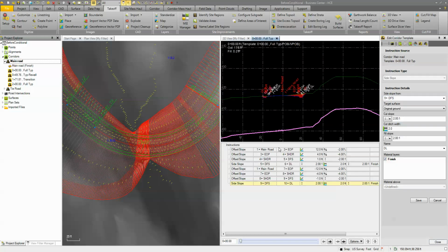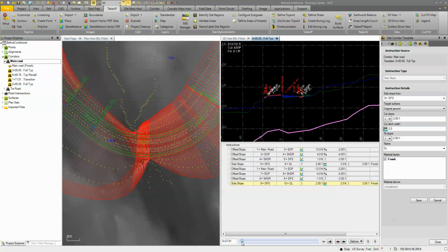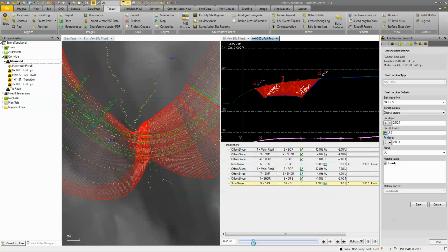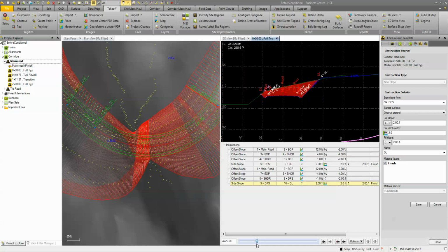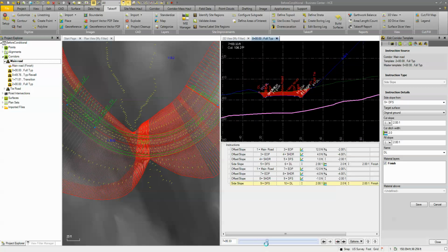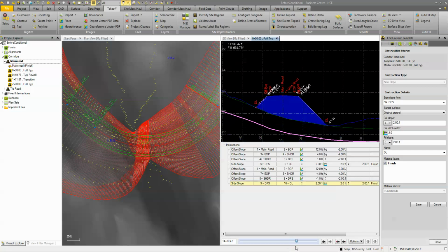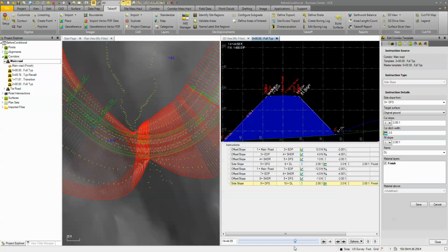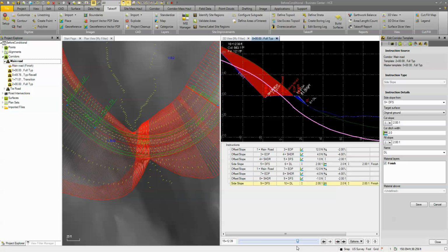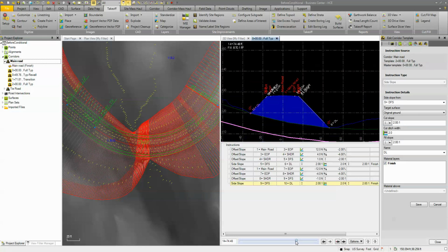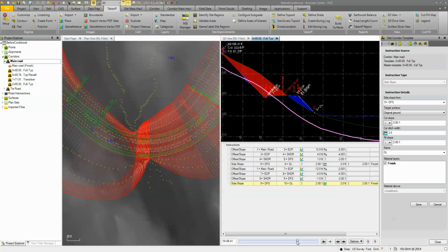And if we look here, as we start at the beginning of the road and we scroll through, you can see that through that retaining wall we're in a cut situation here, but here we're not in rock. We're well above the rock, so we're at a 2-to-1, and that's acceptable. But as we get closer down to this other end, now we're into our fill area, and now we start getting into this area in here. You can see where we start to move into station 15. We start to get into that rock. All right, so we start cutting through that rock.